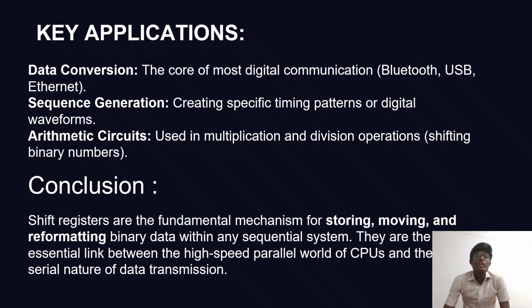The conclusion: shift registers are the fundamental mechanism for storing, moving, and reformatting binary data within any sequential system. They are essentially the link between the speed of parallel CPUs and the serial nature of data transmission. Data conversion, sequence generation, and arithmetic circuits are the key applications.